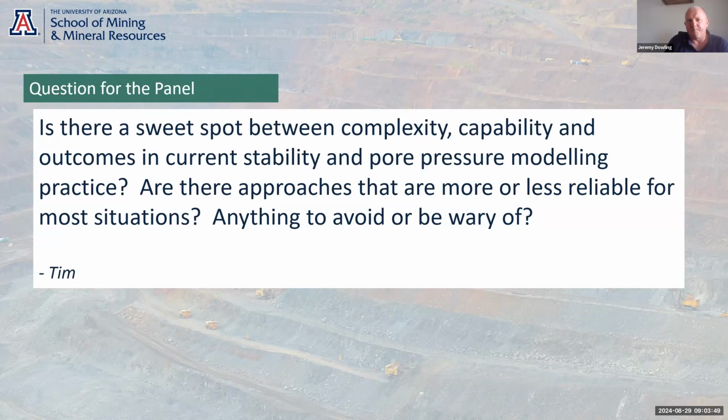So especially with the pit slope pore pressure modeling that is done to inform geotechnical models, I think oftentimes the best approach is to put some relatively simple groundwater assumptions into the geotechnical model, and then complete the design analysis, and then use a good program of monitoring to confirm that the field conditions are compliant with the assumptions of the design, and also to identify areas that aren't compliant with the design, and then use that to target depressurization.